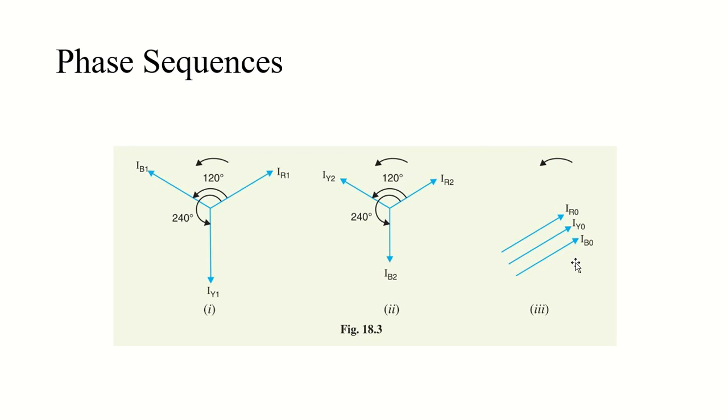And if you see the presence of zero phase sequence, what does it indicate? It indicates that the fault to earth current can return to a system via the star point of that system, right? So it represents the fault condition to ground, and its presence will arise only when the fault to earth current can return to the system via the star point of the system.